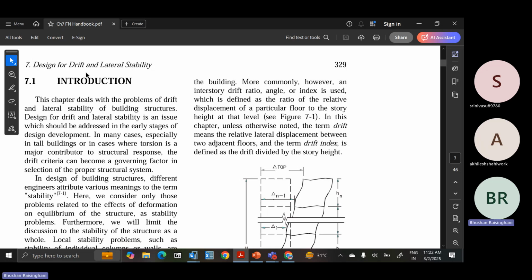So at every story, you will have to find a P, you have to find a delta, and you have to find what the lateral force and the story height H are. And from that, you have to estimate whether this story is having a sway or not. So it is a sway frame or not a sway frame. At inter-story level, you'll also have to check as compared to the full condition as well. So basically, all frames, when you consider the earthquake force and the wind force, have to be considered as sway frames in general.